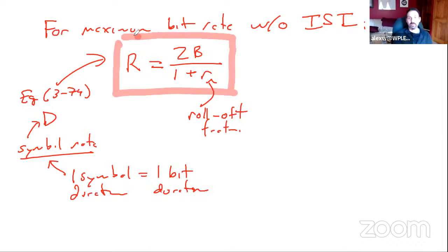So what ends up happening is, you have that absolute bandwidth, but hold the phone, that's not going to be the bandwidth of your symbol rate, right? So when you use a raised cosine pulse, sure, your raised cosine bandwidth is going to go from minus B to B. But in terms of what is supported in terms of the data rate without any ISI, it's this expression. So what you're doing is you're actually normalizing against sort of the tail ends that are actually going beyond minus F naught to F naught, right? The 6 dB bandwidth.